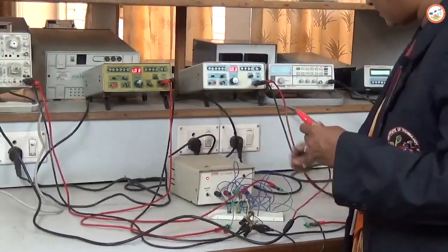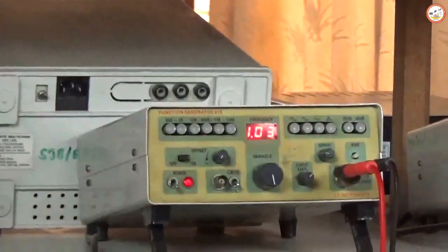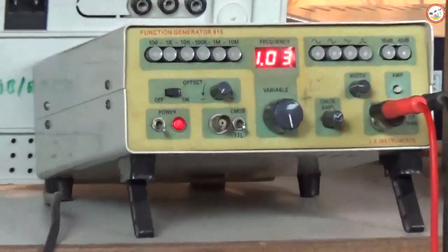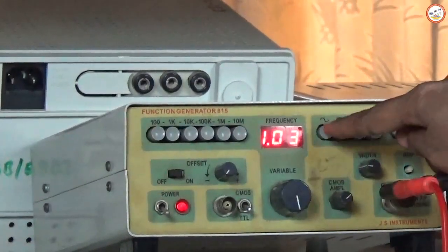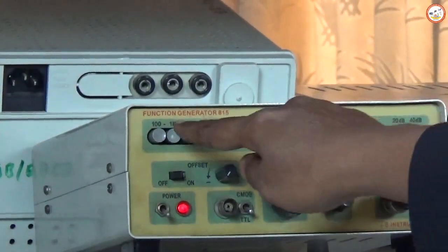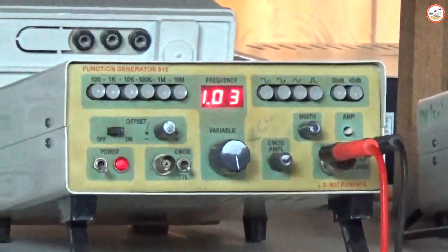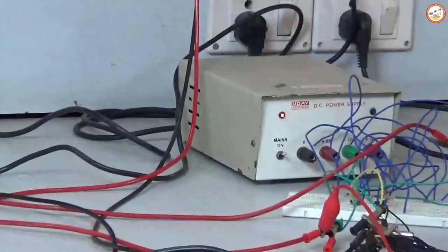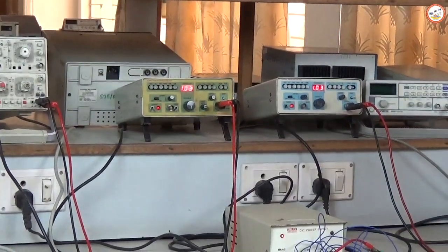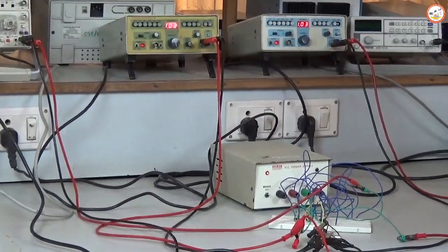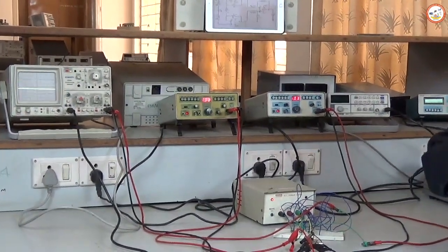Let us consider this is the first signal generator, which is used to generate a sine wave signal. Here we are making use of a 10 millivolts sine wave, 1 kilohertz frequency. You opt for the sine wave from the function generator, and set the 1 kilohertz amplitude as 10 millivolts, because in industrial applications, as I said, the physical quantity once you convert through a transducer you will get a very low amplitude, which is in millivolts. Sometimes even in industrial applications you will get microvolts or nanovolts range. That I need to enhance up to volts.